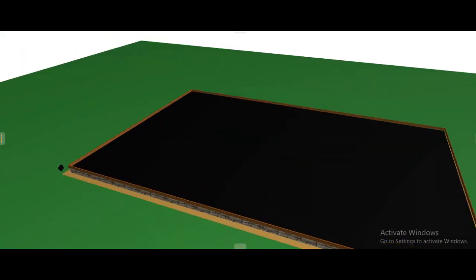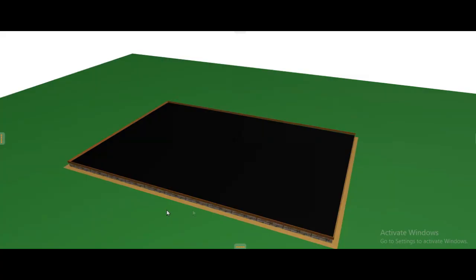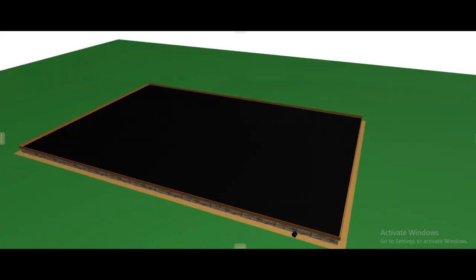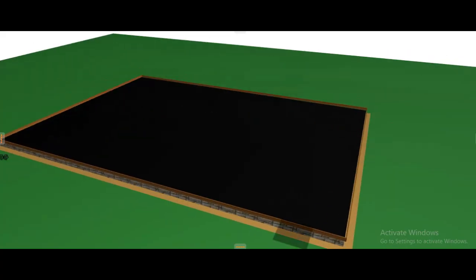So you can see here, we have that formwork that is being done around all the foundation walling. So if I have to get that, I take these two lengths plus these two widths, giving me a total of 40.00 meters. So it is that length of these planks of formwork that I carry on to the Bills of Quantities.